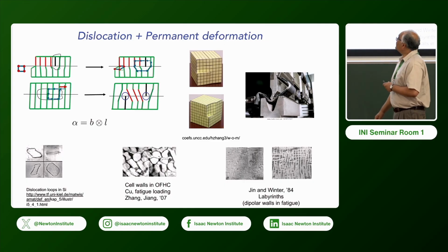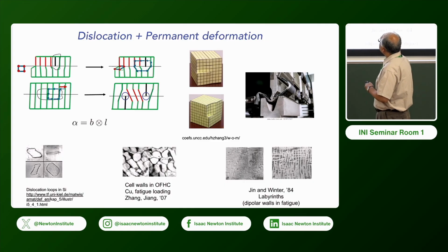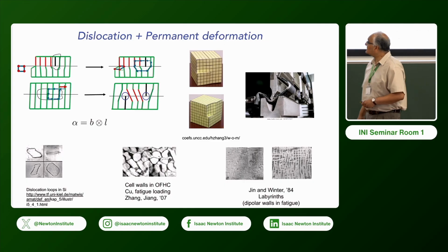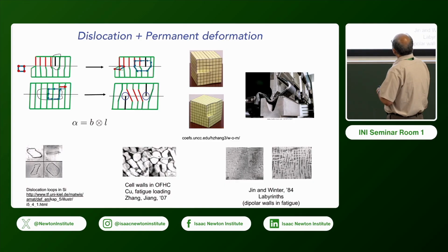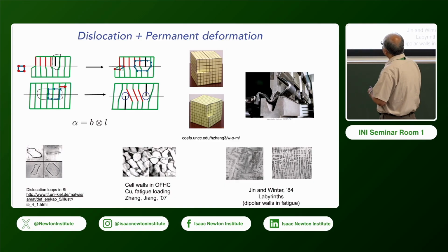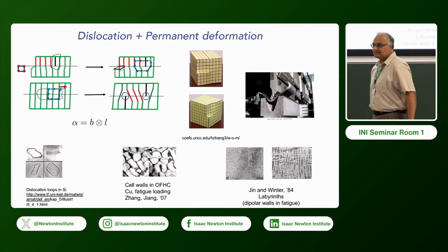Now, okay, so that's that picture. The other thing to keep in mind is how do you characterize a dislocation? So in the deformed lattice, let's say this is where some problem occurs. So you go to good parts of the lattice and you do 3 steps over to my left, and then you go 2 steps down, more or less following neighbors, 2 more this way, 2 more up, and you close this circuit.